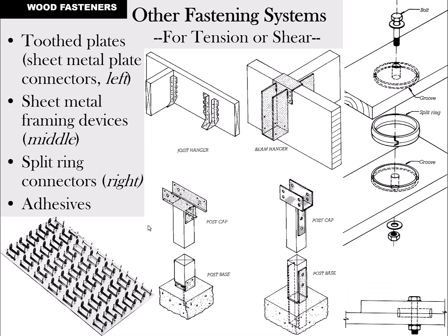So then there's plates that can be used for fastening. The traditional joist hanger is something that maybe many of you have seen for attaching joists, for floor joists or ceiling joists. And they're an important item. There's hurricane straps that are used to hold rafters down, and so we use a lot of metal fasteners. There's special brackets meant for posts to keep the wood off the ground and anchor it to get a good connection between the concrete and the post. You do that with metal very often. There's mend plates that can be driven in for joining two pieces.